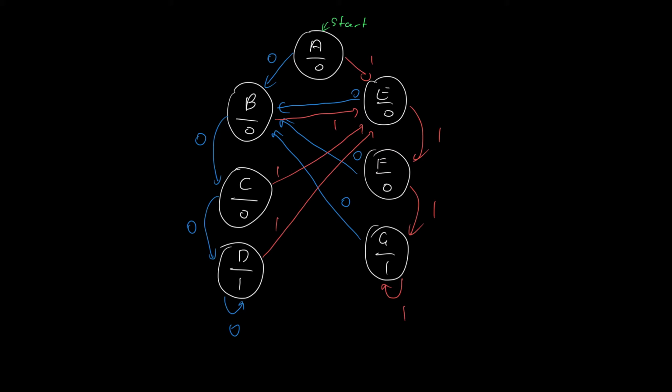Changing state encoding means that we will no longer represent A by 0, B by 1, C by 2, etc. We can change that. Now if we just swap the numbers around here, yes, that might make some change, but we're going to do something a bit more radical, and we are going to use what's known as one-hot encoding. If we have already implemented this in canonical form, then changing to one-hot encoding is straightforward.